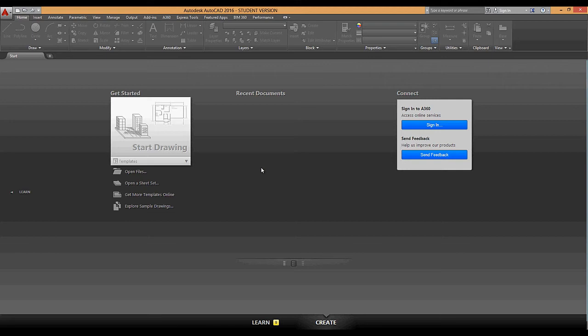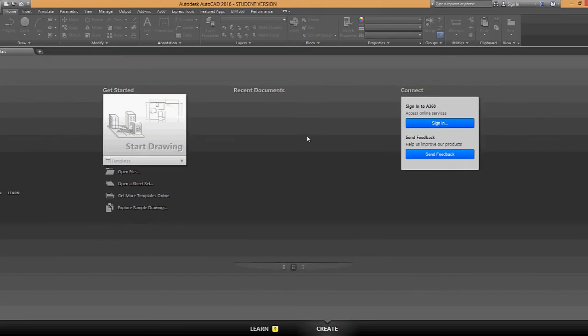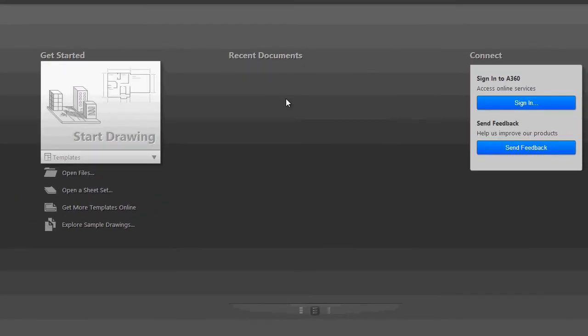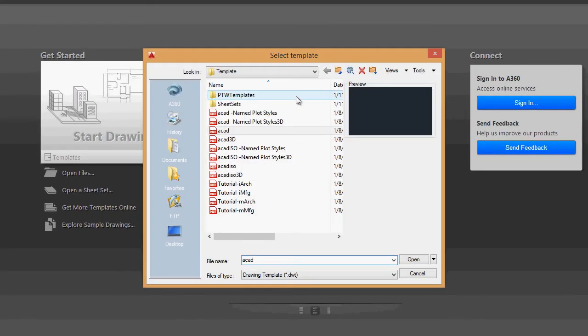or else you cannot work. So if you use the new command, AutoCAD is set up to ask you to select a template. If I go to this screen and go to new drawing, and click on the button for that, AutoCAD will point you to use one of their default templates. This is located in your computer, and these are all the default templates that AutoCAD has created for the system and for the program.